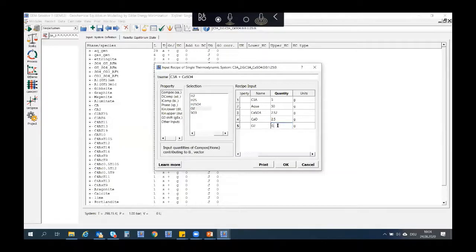And then we often, or I recommend you to put a little bit of oxygen into it. Okay, why do we put oxygen? Because if we do thermodynamic modeling, it takes into account all kinds of redox reaction. And most of our experiments, if we don't work with slag, will be carried out under oxidizing condition. So it's easier just to give the system a little bit of oxygen. It also avoids that due to whatever reason, we might end up in anoxic condition.